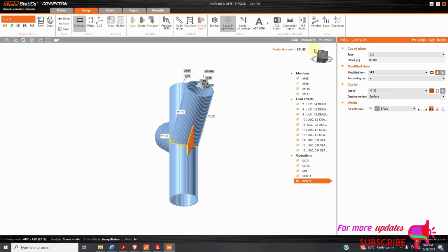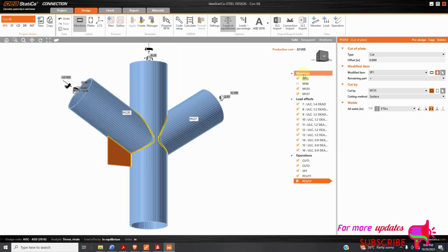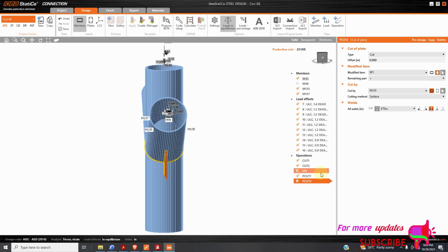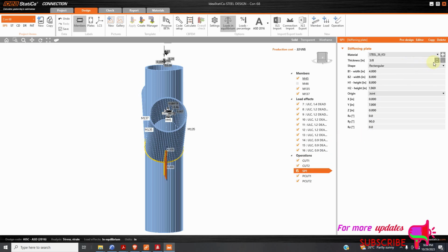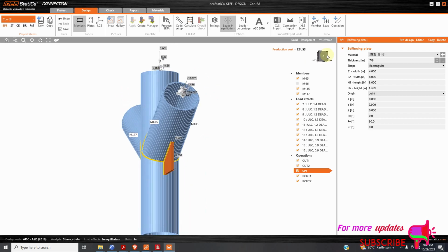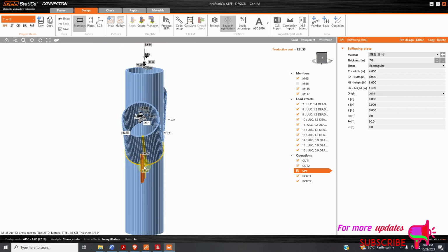So how you can see that well. So cut is very important because when you cut, you create that weld between that connection. So, because of uniformity, I will increase this plate to, as I was using a plate of size 7/8. So I will increase this plate. Remember, the more complex the connections are, the more expensive, and also the size of the plate may determine the cost because this plate is thick, so it will be costlier.